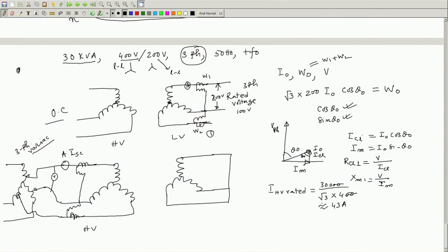So, you have to choose an ammeter which can read 50 ampere, say, and similarly the wattmeter current coil, but the line to line voltmeter rating should be very small, maybe 5-10% of 400 volt. 5% of 400 volt is only 20 volt.